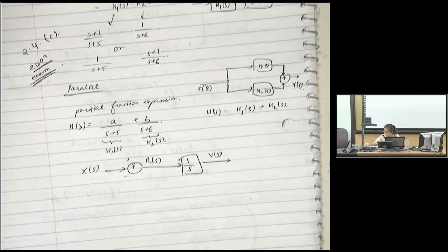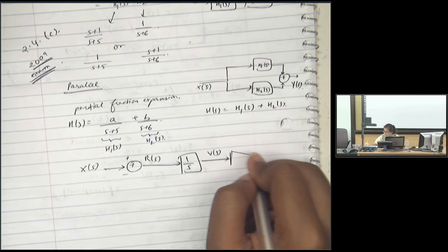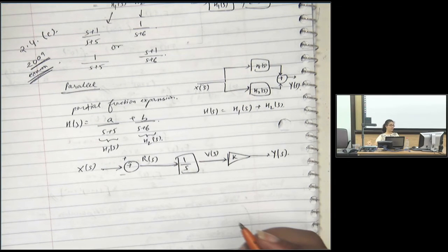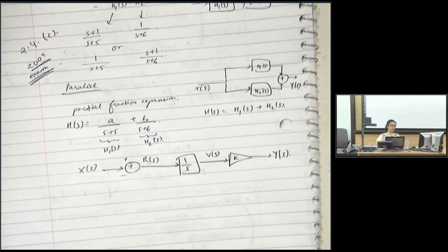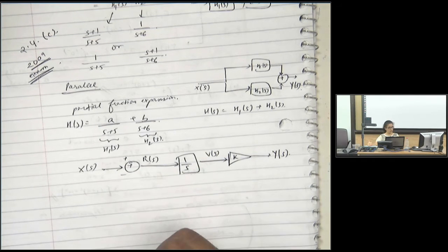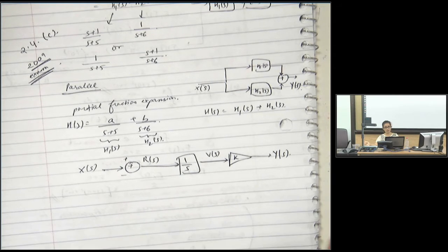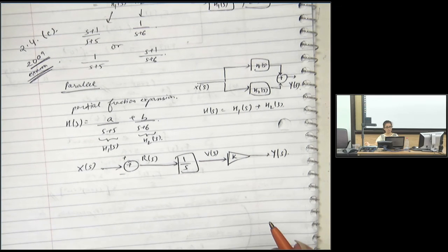Are tap delay lines okay with block diagrams or something different? Because it was on one of the older exams. They're the same as the block diagrams, just another name. So a tap delay line is if I take my input and delay it a lot of times, in succession, one after the other, and then add all of it together. That's my tap delay line.